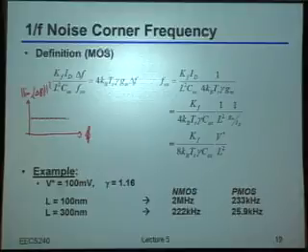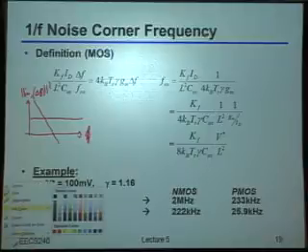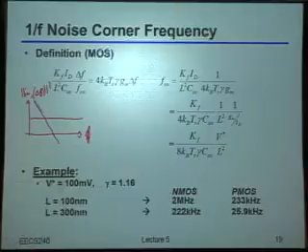then we said that that's basically white. In other words, you see something kind of flat like this, right? Well, it turns out you also have to add in this flicker noise. And we said a second ago that it has this 1 over f kind of profile. So if I looked at the total noise coming out of the device, well, when you add those two things together, and again, of course, you have to do this in variance, you'll see something that looks like this blue curve that I'm drawing here, right?